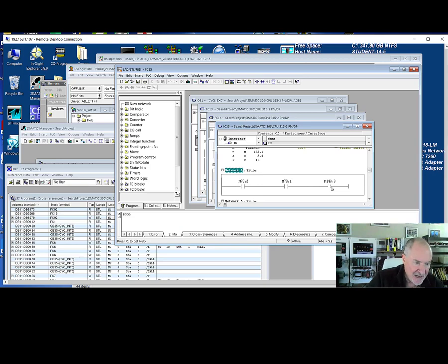And I'm going to write this down. Once again, I don't have any kind of bookmarks or anything, so I'm just going to write this down. I'm going to say FC25, and this is network 4, and this is where the coil is. So I may want to create my own shorthand here, put a little equal sign, and then put M143.3, and the things that change it are M70.2 and M70.1. So you see what I'm doing here.